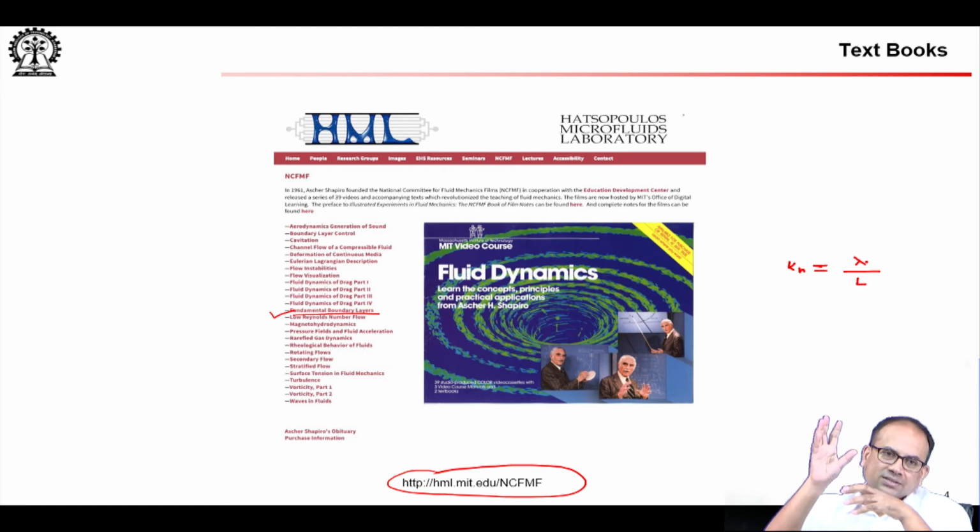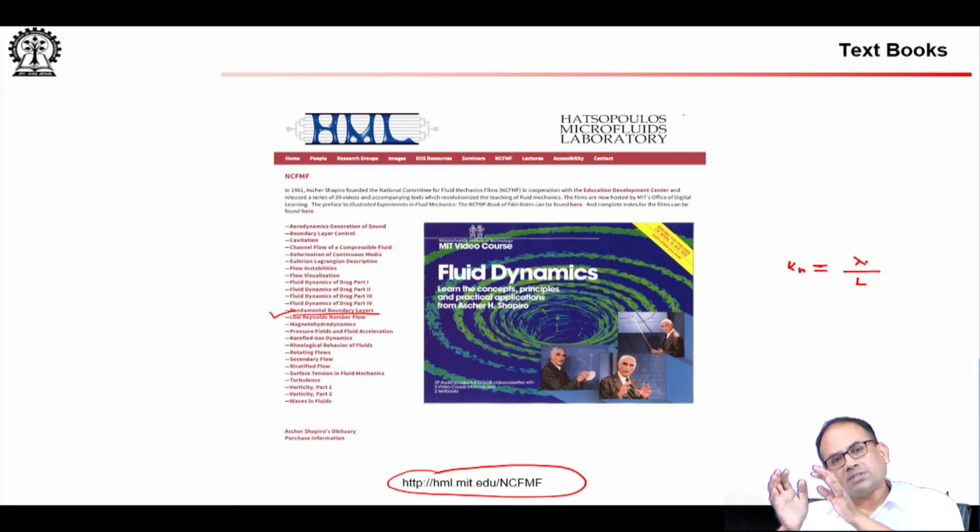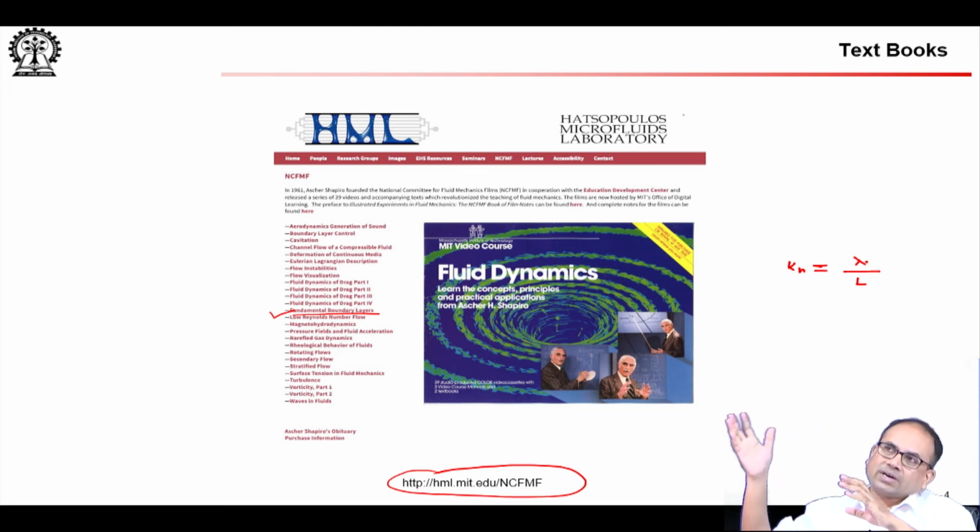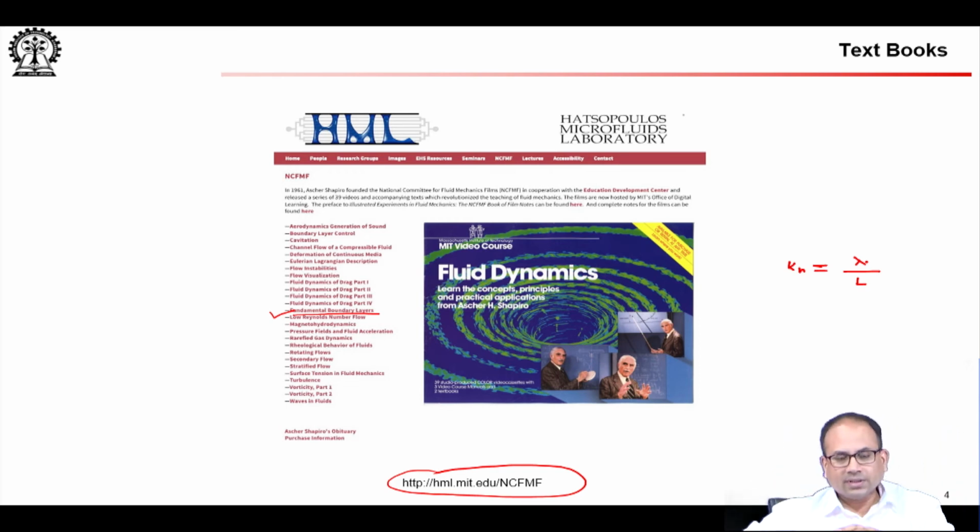So, re-entry vehicles, you can not only have slip, you can also have situations where you have to discard Navier-Stokes completely, and you have to use some kind of molecular collision simulations to find the forces and so on on the vehicle. So, if you are coming back from orbit, not from the ground but from outside, then you will hit all these ranges of Knudsen number.